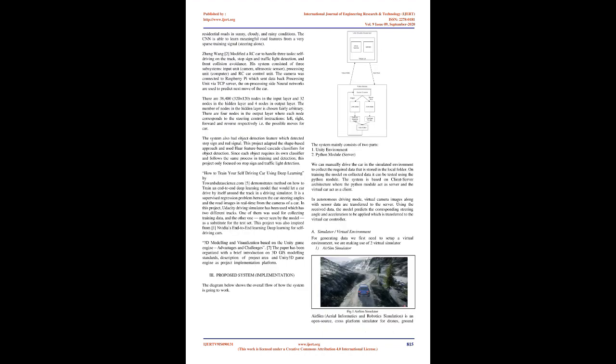In this tutorial, we are training a model to learn how to steer a car through a portion of the landscape map in these simulators, using only one of the front-facing webcams on the car as visual input and 4 distance measuring sensors. Our strategy is to train an end-to-end deep learning model to predict the correct driving control signal, in this case the steering angle, given a frame from the webcam and the car's current state parameters: speed, steering angle, throttle, distance sensor readings, etc.